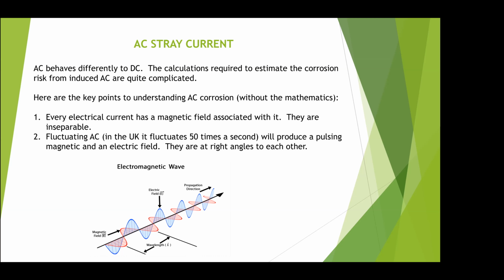And what we have to do is work out the impedance of the pipeline, the distance from each of the different wires in the overhead power line, and what the relation of those wires is to each other, because that affects the phases. And once you've worked out the impedance, which is the same as resistance in many respects, then you can work out how much voltage gets induced in the pipe. Again, there's a lot of detail in the new standard that we've written.